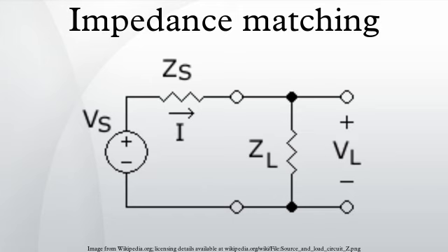In electrical systems involving transmission lines, where the length of the line is long compared to the wavelength of the signal, the impedances at each end of the line must be matched to the transmission line's characteristic impedance to prevent reflections of the signal at the ends of the line. In radio frequency systems, a common value for source and load impedances is 50 ohms. A typical RF load is a quarter-wave ground plane antenna.